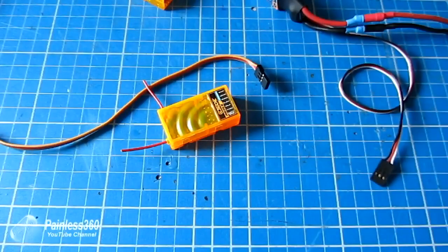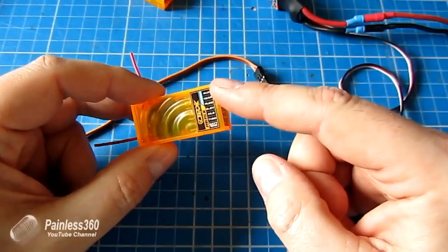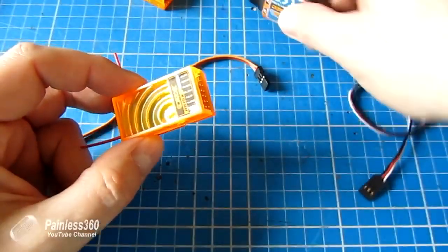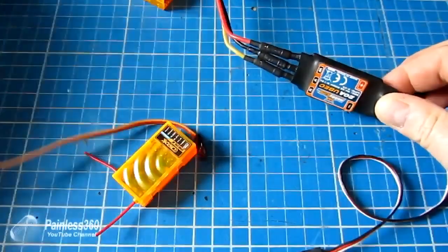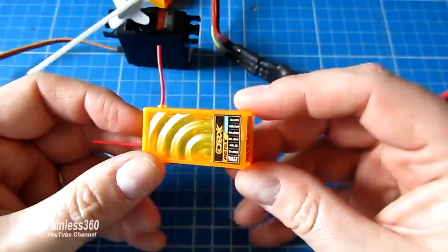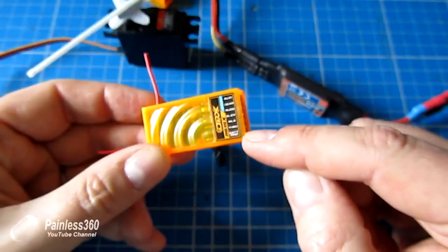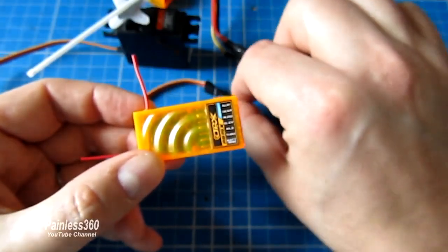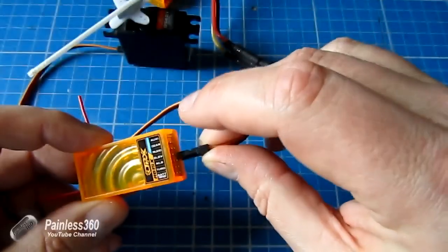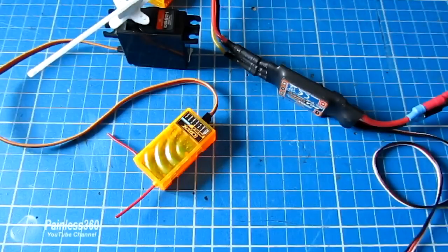Next thing to talk about then is how do we actually get the signal from the controller on the receiver to something like the speed controller or the actual servo itself. Well, the amazing thing is that it actually is sending out little microscopic pulses on each of the channels, or if it's PPM, on one individual cable. Now when I plug the servo into the receiver, what happens is down that signal wire, the receiver is sending little pulses that are in direct relation to the position of the control on the radio.